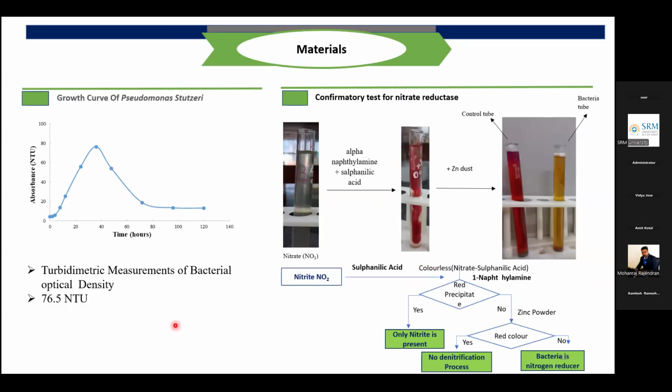We need to create air bubbles or gas in such a way that the gas will replace part of the water in the system. So we identified a particular bacteria called Pseudomonas putrefaciens, and this bacteria will produce nitrogen gas. There are certain advantages with nitrogen gas, so in order to have more effectiveness in the replacement, we used this bacteria to produce nitrogen gas.